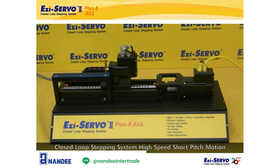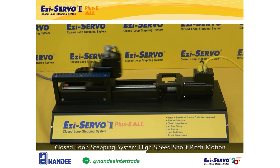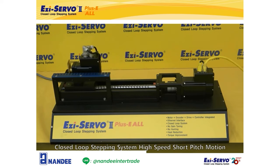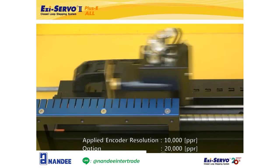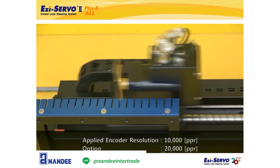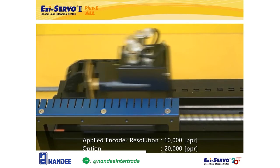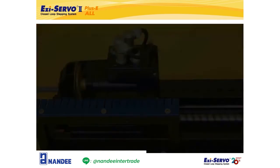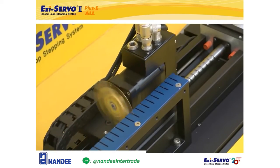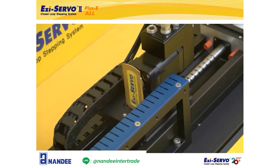You can see the bar and plate engage without collision while the two motors are running in high-speed short-pitch motion. Because Easy Servo 2 Plus E All is a closed-loop stepping system product, accurate position control is possible with a high-resolution encoder, up to 20,000 ppr, and it is optimal for high-speed, short-pitch motion because of the characteristic of a stepping motor without hunting after stopping.